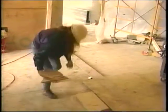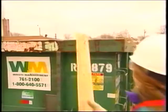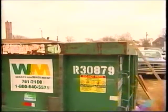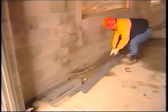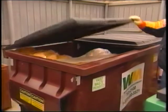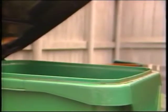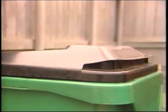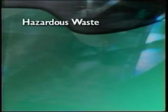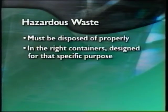Pick up any object or piece of debris that someone could trip on, even if you're not the one who left it there. Be on the lookout for form and scrap lumber with protruding nails, and make sure to dispose of it properly so no one gets hurt. Glass and other sharp objects, such as sheet metal, must also be properly disposed of. Use trash containers with lids for the collection and separation of all waste materials. Make sure to replace lids after you've disposed of debris. Lids should have a firm fit. Hazardous waste must be disposed of properly in the right containers designed for that specific purpose.